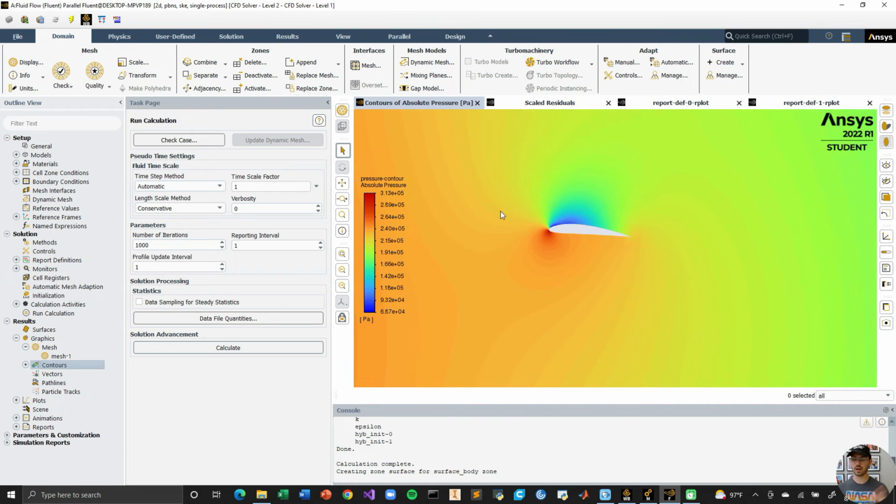When a wing is flying through the air, the thing that produces lift isn't just on the bottom of the surface, air is coming in and then bouncing off at an angle and pushing it up. That does play a role in this, which is why we have the angle of attack. But fundamentally, and even that is built on this concept here, what's really happening is you have higher pressure air below and lower pressure air above the wing.